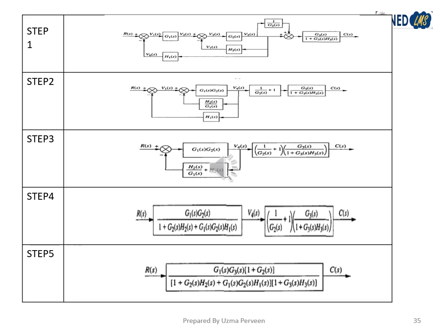It is a simple feedback loop, and we have simplified this using the transformation eliminating a feedback loop. And then in step number 4, these two blocks are in series, so we have combined blocks in series by multiplying their transfer functions. So we have a simplified, single transfer function for this diagram.